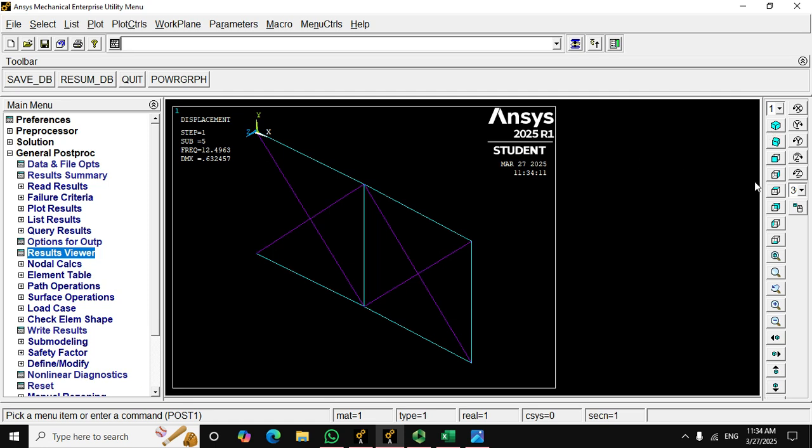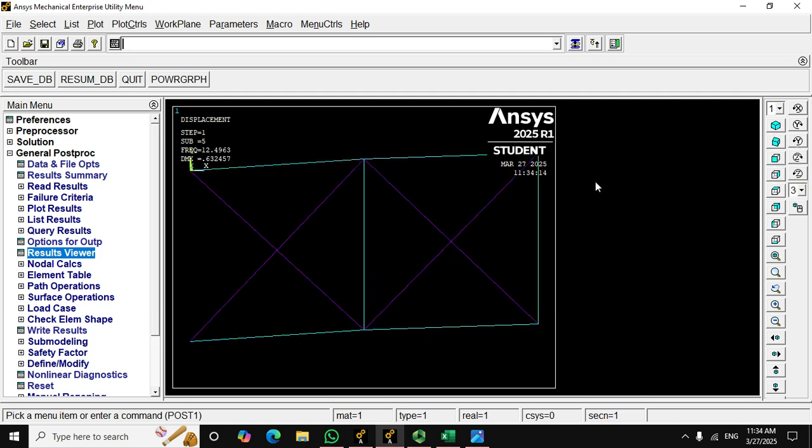You probably knew this fact, but we didn't look at this on a truss structure like this. So we had nodes that were free to move. We had 1, 2, 3, 4, 4 of them. In 2D they have 8 total degrees of freedom. So it means that in 2D we are going to find only 8 frequencies.